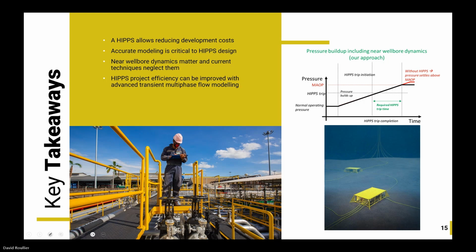How are you addressing compressibility and fluid behavior, mass transfer between phases during pressurizing? So in this scenario, everything is handled by the simulator itself, by Olga. You might have a compositional tracking model or a tab file, depending on your needs. So that's basically resolved within Olga itself.